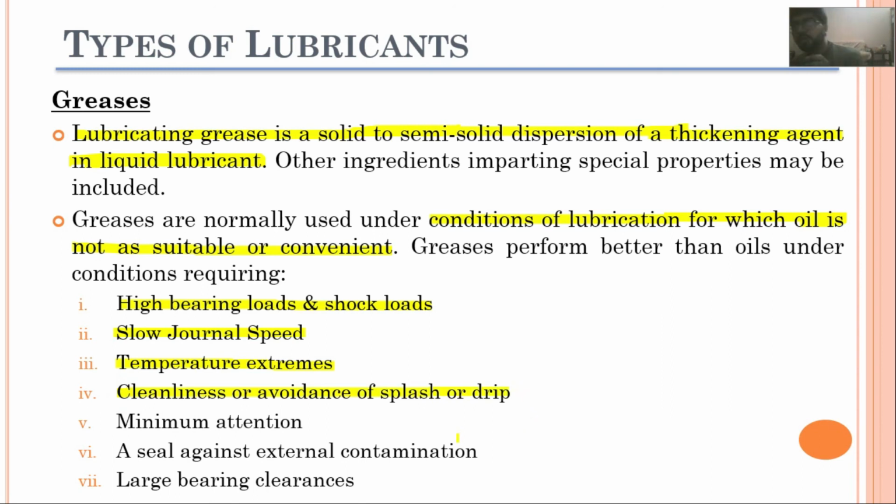In liquid lubrication, we have a splashing of the liquid oil throughout the moving components of the IC engine. In cases where we do not want the splashing of lubrication oil, we prefer to use greases. Greases also require minimum attention, whereas lubrication oil will have to be changed over and over again after some running hours.